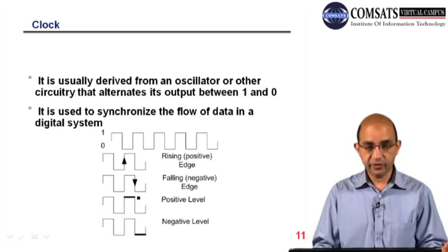So this is the level, because we have already discussed the level, because latches are level sensitive. So this is the positive level, and this is the negative level. That's what we were talking about, that latches will continue changing their state during this positive level. So there will be transients during that level, so it depends on the length of this level.